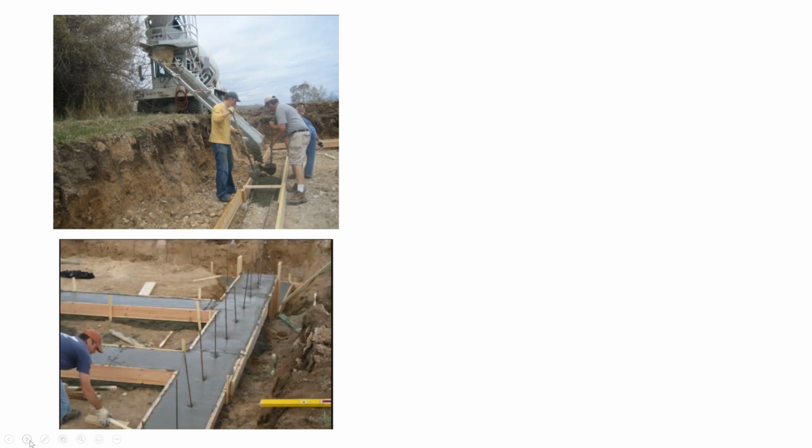So once they've dug the hole, they frame up these for the footers. You can see the rebar that they've placed in there, because the rebar is going to run up through the walls to help give that concrete some support. So you can see that these areas here are obviously going to be supporting walls in addition to this exterior footer here.